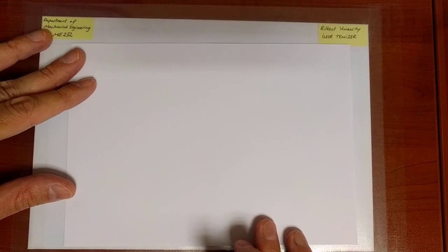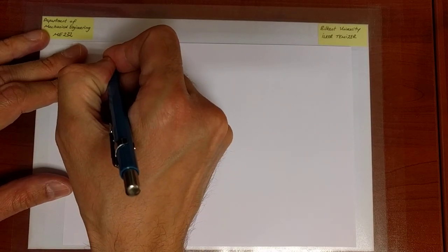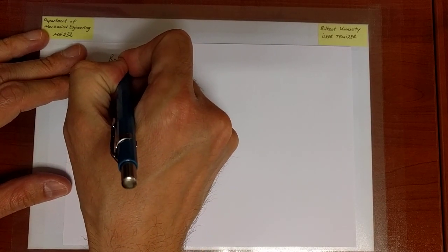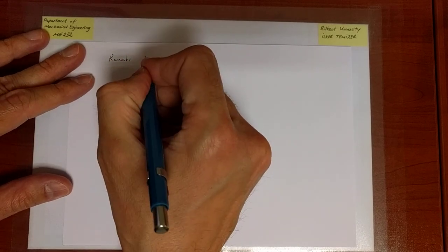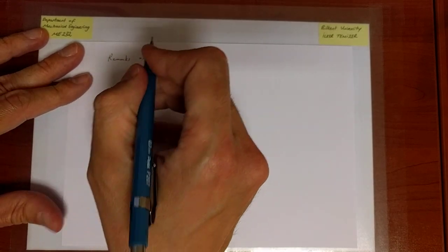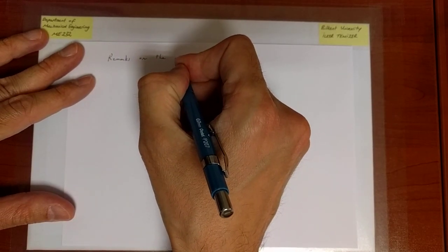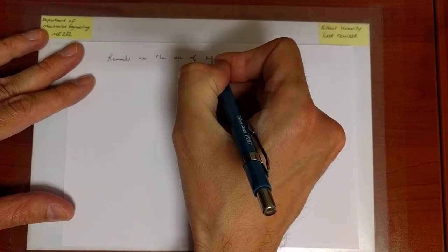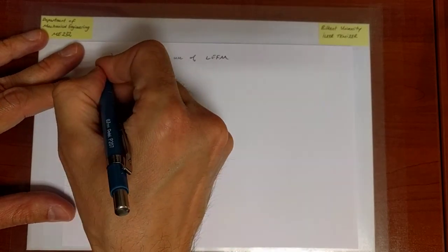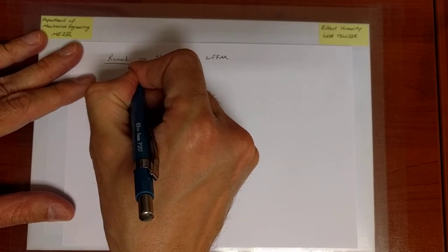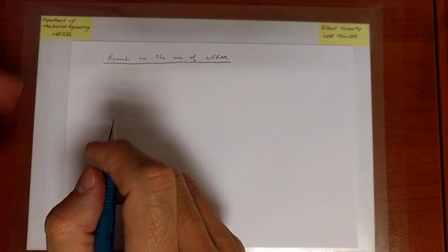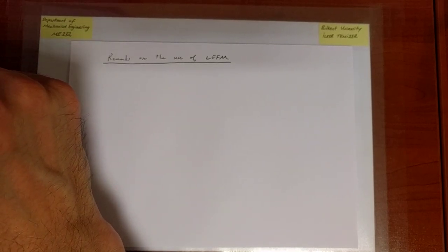We would like to comment on a number of issues that arise when we are trying to apply linear elastic fracture mechanics to different problems. So let's make some remarks on the use of LEFM. Remember, we're doing linear elastic fracture mechanics, which essentially addresses the fracture of brittle materials where there's little or no plasticity, and for that matter, any other inelastic process that is going on.